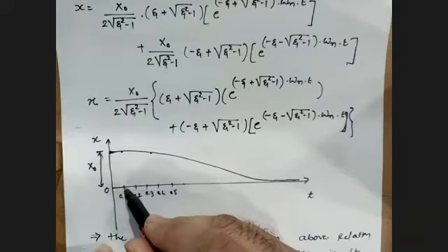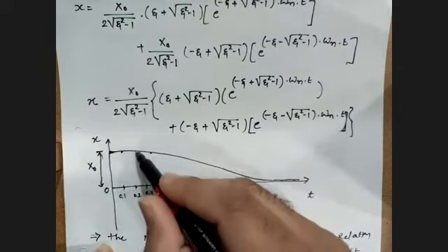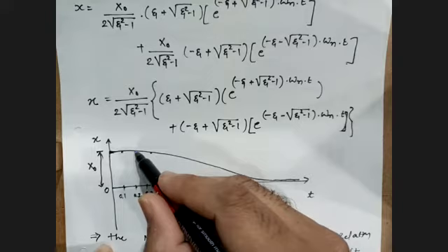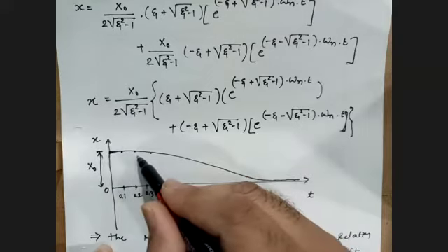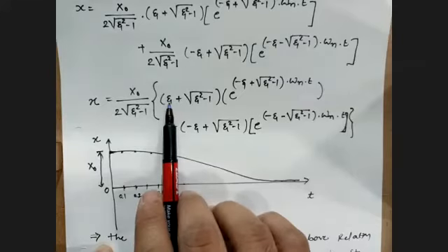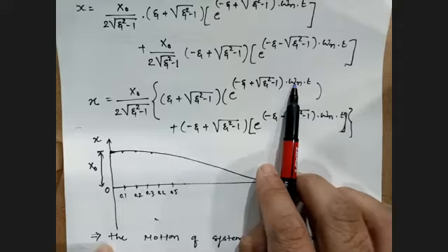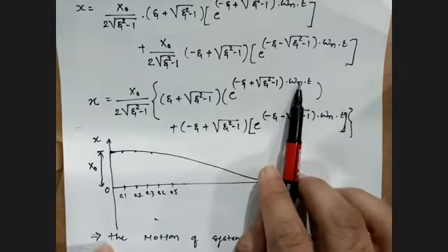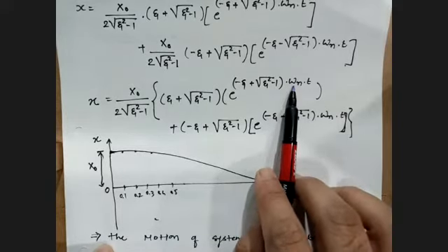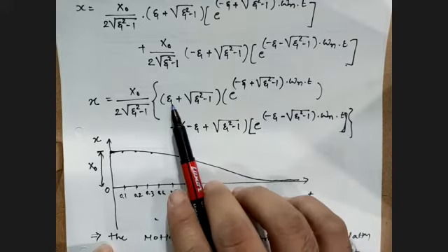If you are at 0.1, this could be your x value. If it is 0.2, this will be the x value. So this value of x depends on certain parameters like zeta, x0 and the natural frequency. For a particular system the natural frequency remains constant if you do not alter the spring and mass, but you can vary the damping coefficient.